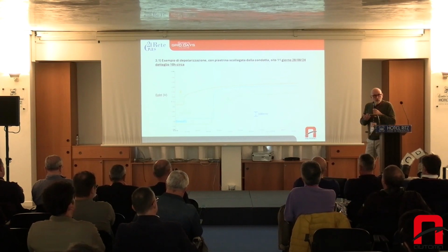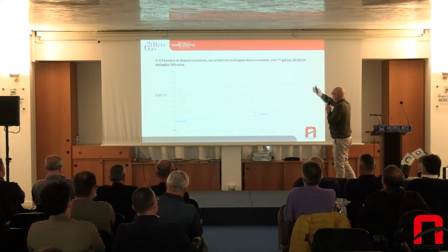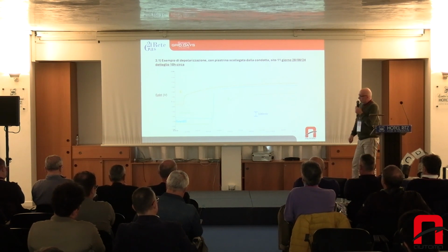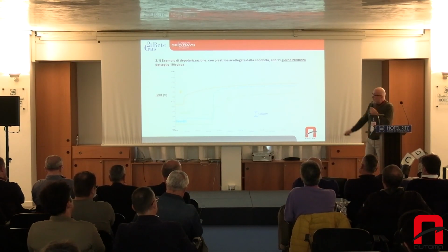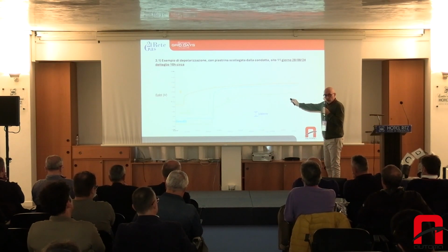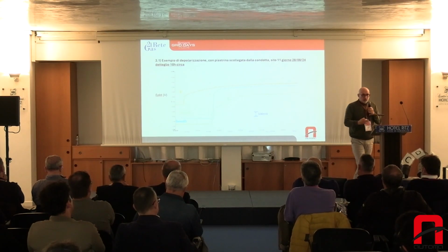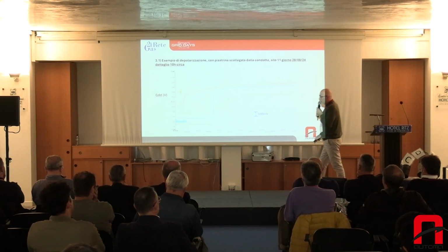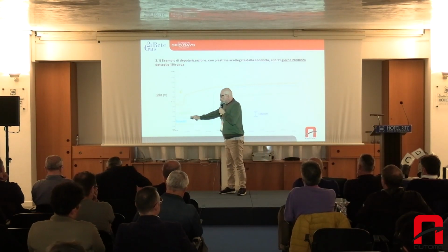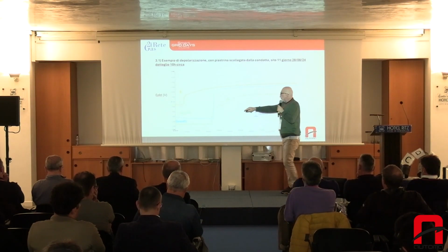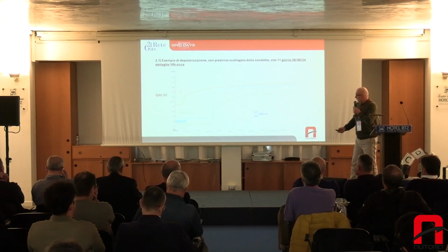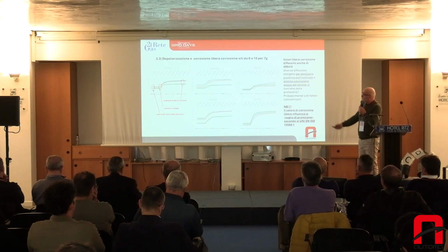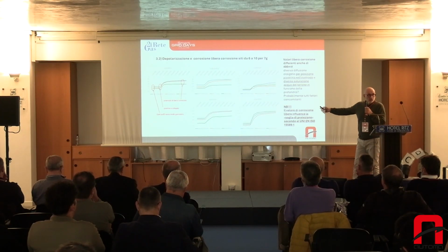But then we said, where should we start from? Why do I have these differences? What kind of plates are we using? In this case, we decided to disconnect the plates and measure free corrosion. The same site where we have 4 devices, we disconnected the plates and checked how they depolarize. We checked the different potentials. We saw it before. Let's see how they behave. This is after 1 day, and this is after 1 week.